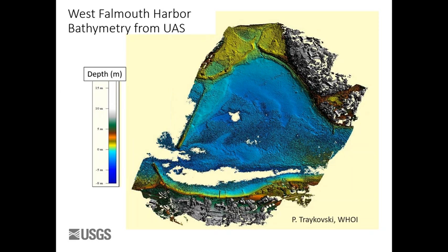Still pictures work better. There's a lot more detail in still pictures. So in the end, the way we program the drone is to fly along and click, and we're shooting to have each image overlap by about 60% along the track line, so there's a lot of duplication, and about 50% across track on the parallel track.